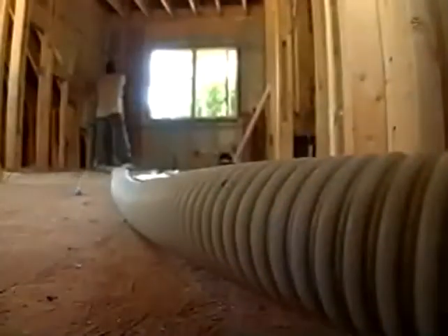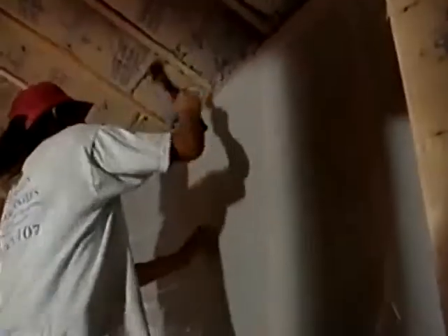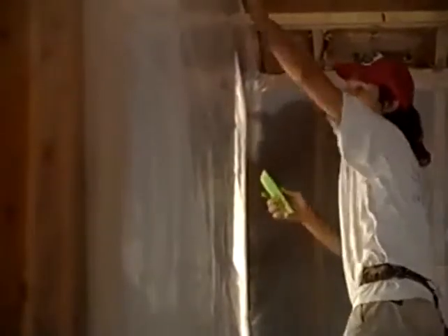Many different materials can act as vapor barriers. When installing dense packed cellulose, the nylon reinforced polyethylene that holds the cellulose in the wall cavity can act as a vapor barrier. When installing sprayed cellulose or unfaced fiberglass bats, stapling sheets of sealed polyethylene tightly over the stud assembly provides a vapor barrier. Coated kraft face paper on bat insulation can be an effective vapor barrier. Any material that does not allow moisture to pass through it can act as a vapor barrier.